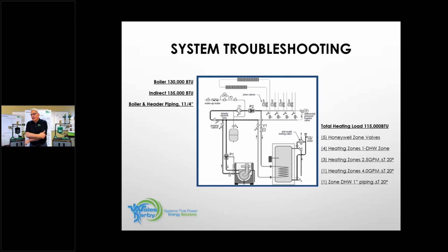I'm being sneaky here. You know, we threw zone valves up there. So unless you really know flow rate through zone valves, I'm really leading you down the path here. Unless you really know flow rate through zone valves, you may be confused. I got on here change zone valve, and that's a good answer, but which zone valve am I changing?